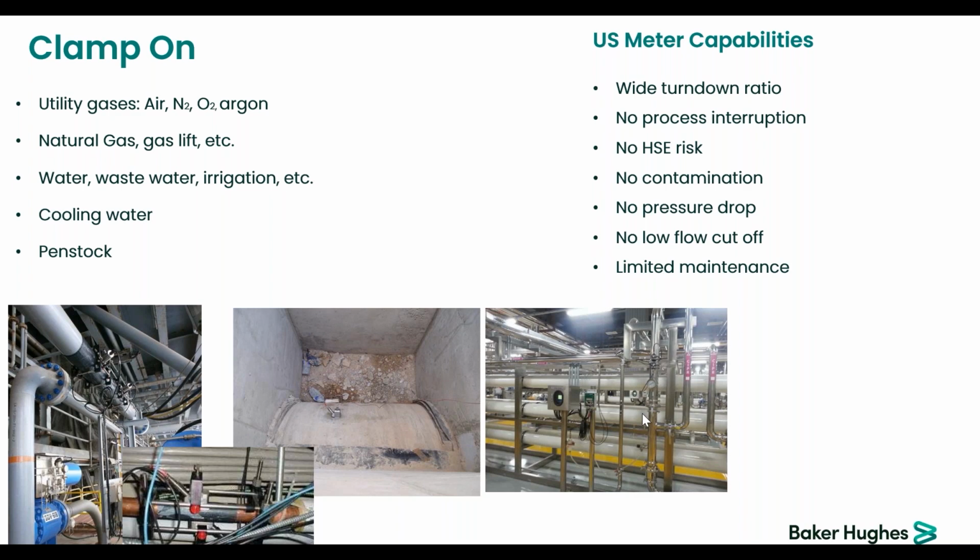So we will need to understand, because 40 Fahrenheit is not very large as a spread in terms of temperature, but it will impact the velocity of sound, and we will need to ensure that the window, once open, is covering the range of the velocity of sound that will be impacted by the temperature change. So that will need to be set during the programming of the meter for installation.